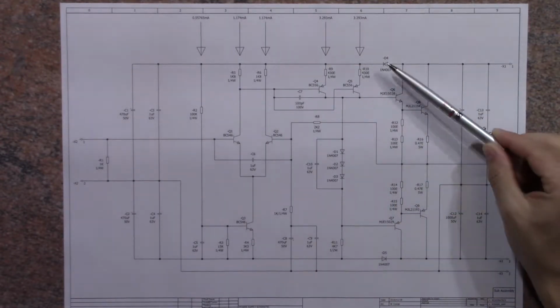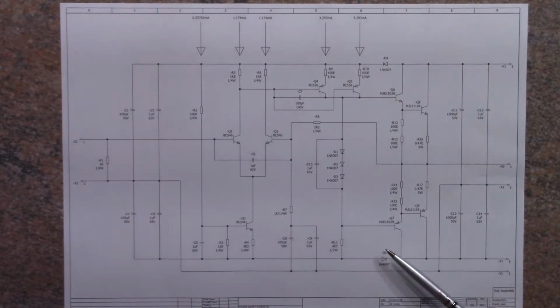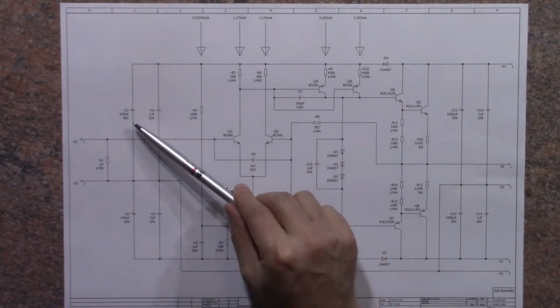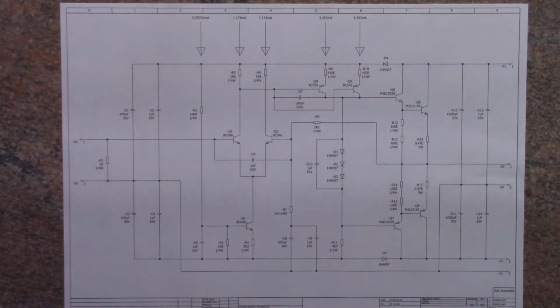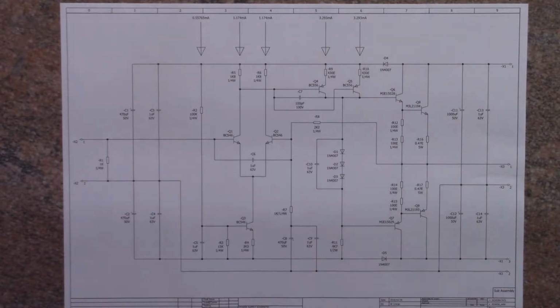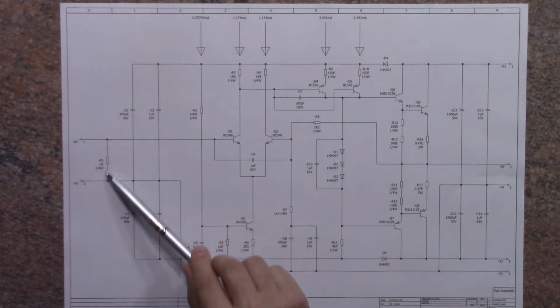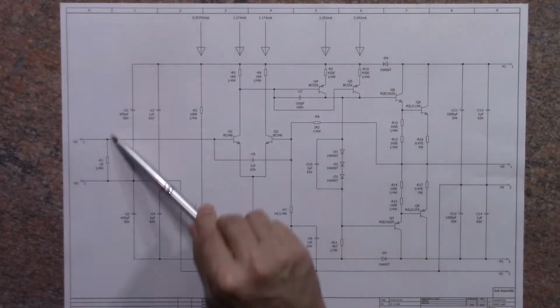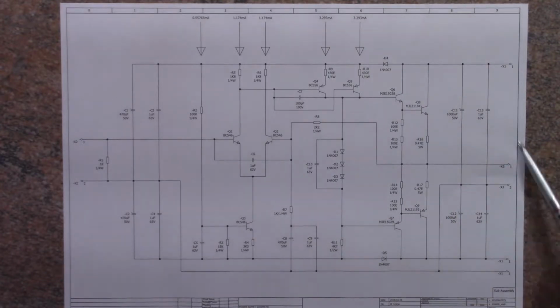I've also put a diode over here and over here, which means the low current part of the amplifier has its own smoothing capacitors over there and over there, as well as bypass capacitors in parallel with them. The power section has its own capacitors. This creates a cleaner supply on the negative feedback section than what you'll get on the output stage.